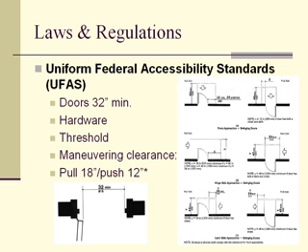At that point, you have to get out of the way to be able to open that door. So for a person in a wheelchair, and we could also think of somebody on a walker, if you're pulling that door, you have to put that walker or that wheelchair clear out of the swing of that door to be able to open it all the way, and after it's open, be able to move in and go through that door.